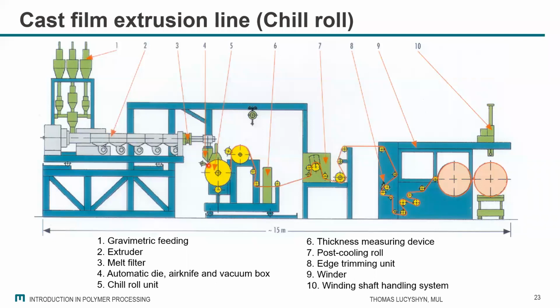And then here the core part of this is the die, which is a slit die. Basically, the slit is a very wide rectangular slit. So the cross-section is a rectangle which is very wide and very thin, like 50 micrometers thick, but maybe 1 meter wide. And that's basically the shape of a film. And this film comes out in a melt state, and immediately after exiting the die, of course, it has to be frozen, otherwise we wouldn't get a defined shape.